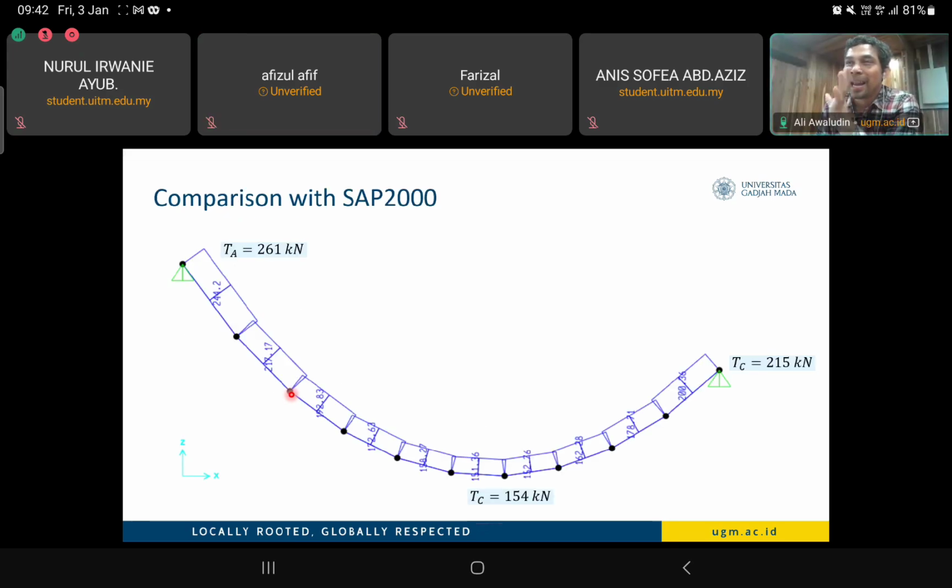Yes. In much of the literature it is always said that the cable system is an efficient one, because in a cable we only have tension forces. We don't have shear forces, we don't have compression forces, we don't have bending moment. So we use the whole cross section of the cable multiplied by the yield strength of the cable. It becomes the tension capacity of this cable.